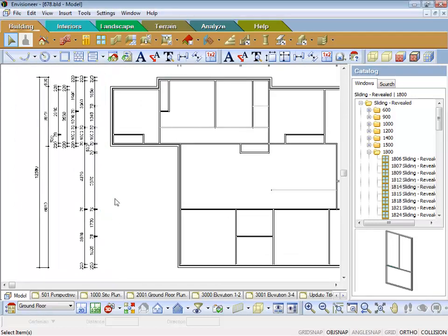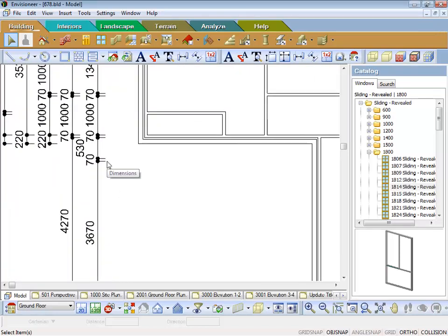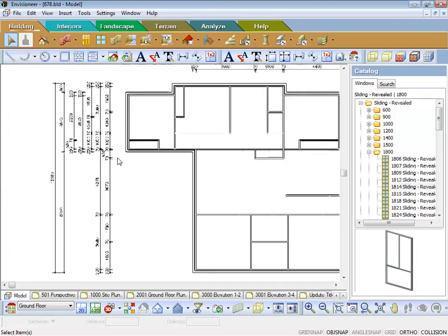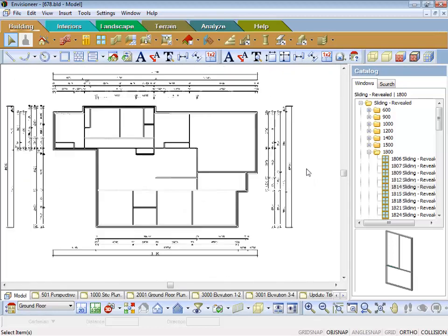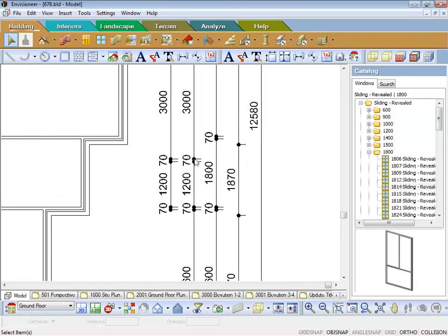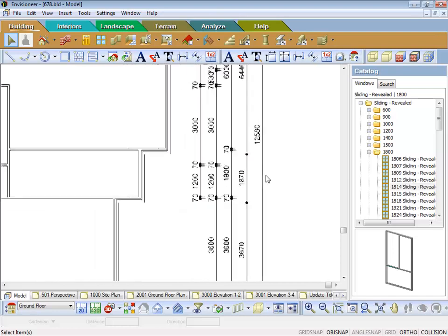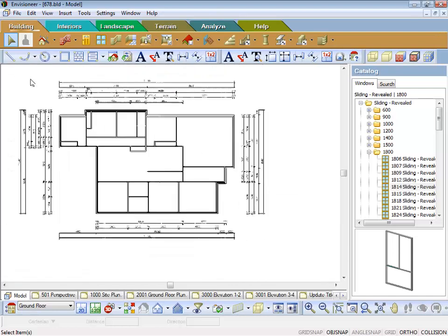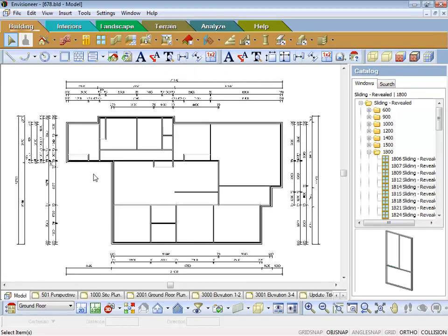The issue there is, some people say that there are Australian standards and they should be pointing to the building, but if you do it my way, it's right on one side, but I come across to the other way, see the extents are pointing away from the building. Otherwise, if I did it to what they believe Australian standards are, I'd have to go from bottom to top for my right hand dimensions. It would point those into the building, and therefore my text would be all needing tidying up. So that's the reason I go right to left and top to bottom.